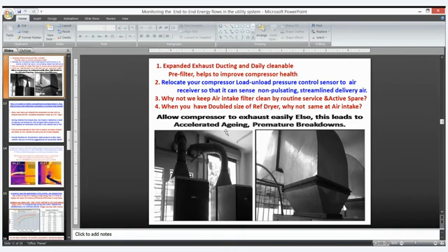And one more point: for all the compressed air users, we have the pressure control sensor, a 4 to 20 milliamp, 0 to 10 bar pressure transducer. We are trying to have it within the compressor hood itself, and that is facing an artificial hike in high and low, load cut in, cut out. Instead of that, it can be just relocated to the receiver. This will smoothen the pulsations. You can measure the streamlined laminar flow of compressed air, and thereby the cut in, cut out can also be altered to optimize to the production or to the system as it is.